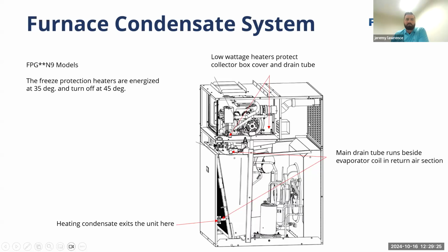So we've had great success with these units. Even though it is a compressor-bearing unit inside the living space, it is very well insulated. We never get a question of sound issues coming from these units, and they've done an excellent job of providing insulation and protection to make sure there's no frosting or condensate building up. And that's one of the reasons that open return air around the unit is important: it maintains an airflow from the return that keeps any moisture from building up on a cold surface.